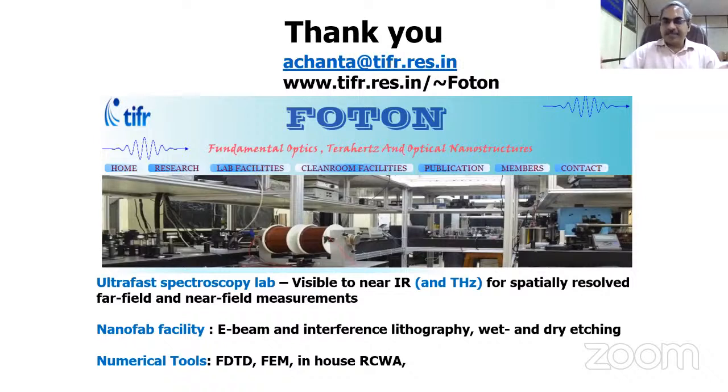There is also, for example, nano imprint lithography. You need a mask, and then with UV exposure or local temperature curing you can stamp these to have large area writing. Even with electron beam lithography, one of the drawbacks is that you get finer features, but writing over a large area will take hours, 10 hours, 18 hours, something like that. So you can use simpler nano imprint lithography to make large area patterns.